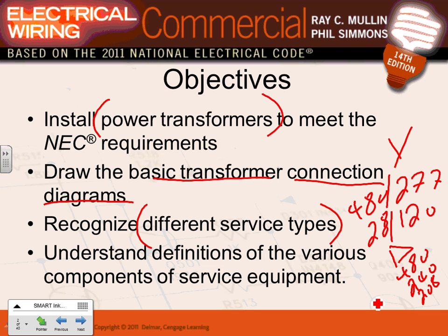The reason why transformers are very important to the service is because the transformer will decide the voltage level. That's why you always start with a transformer. Like I told you before, if you have your choice in a commercial building, what voltage would you use? 480/277, if you have your choice. Why? Higher voltage, more efficient equipment. What's the problem with this one? You can burn all your lights at 277. The only problem with having a service of 480/277, anybody knows why? We have another transformer to step it down to 208/120 to get the receptacles.